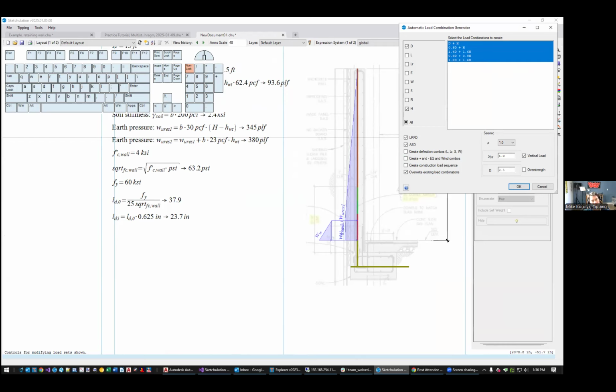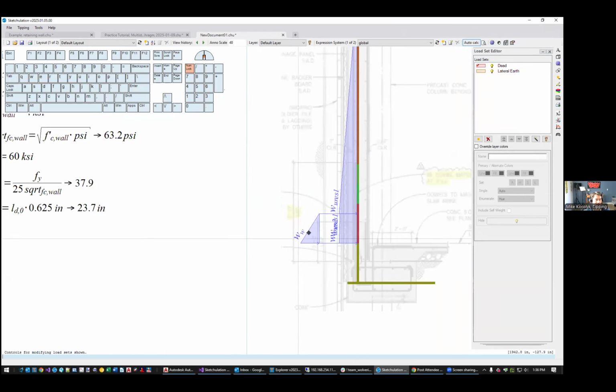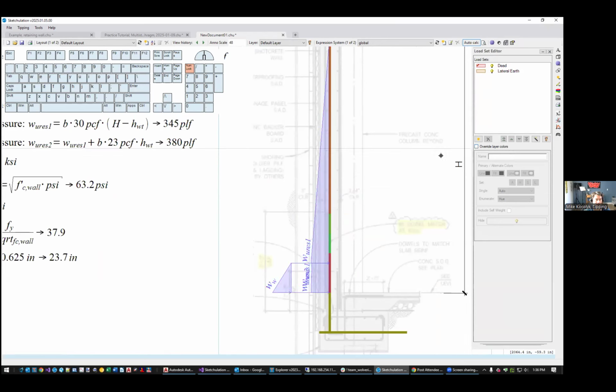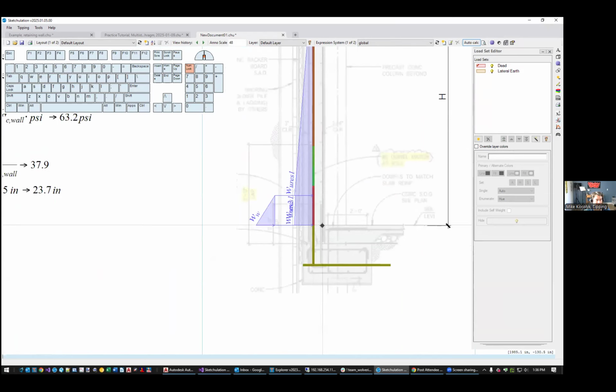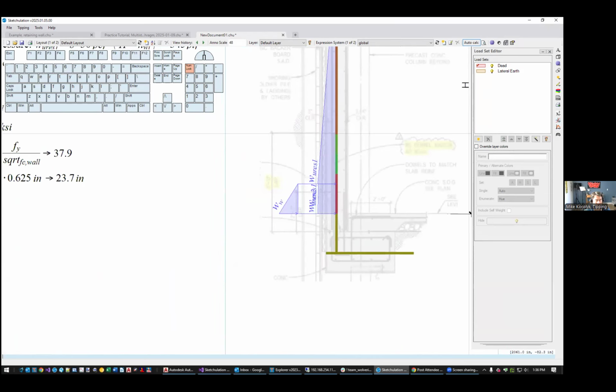And just do a brief check on the rest of these. They all look good to me. And I click OK. And now these guys are all lateral earth pressures, so I assigned them that way. Double check that they were assigned properly, and I'm good to go. So I've got my loading, I've got my frame element type. Now I need to think about supports.